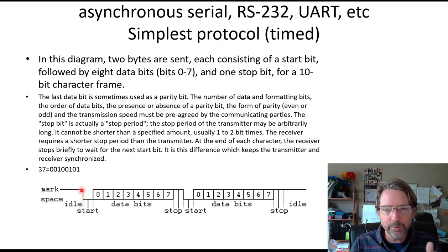if it's 9600 baud, in 1/9600th of a second after this, the first bit of data is going to come in. So whether it's a 1 or a 0, you'll either get 5 volts or 0 volts, and then one more bit time you'll get the next bit and the next bit and the next bit, and they just get sent according to the baud rate.